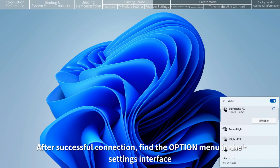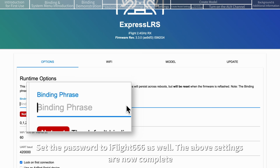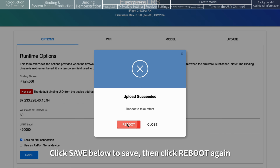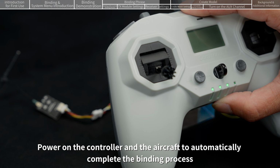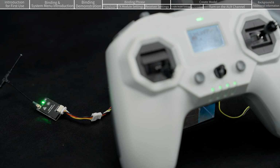After successful connection, find the option menu in the settings interface. In the binding phrase field here, set the password to iFlight666 as well. The above settings are now complete. Click Save below to save, then click Reboot again. Reboot and exit. After the binding phrase is set on both the TX module and the receiver, power on the controller and the aircraft to automatically complete the binding process.